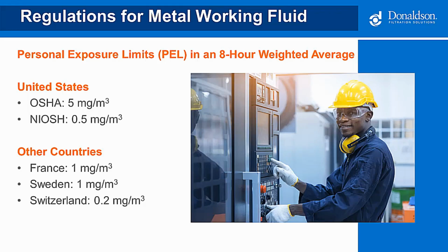In fact, the UK used to have a 1 milligram exposure limit, and they dropped it because they found it did little to protect workers and provided a false sense of security. So they changed it to ALARP, meaning as low as reasonably practicable. Now, before everyone starts panicking, you need to know that these goals can be achieved with a well-designed and maintained system. OSHA actually has a mist control best practices manual on their website that you can access, and the fact that you're all here today means you care about getting it done right.